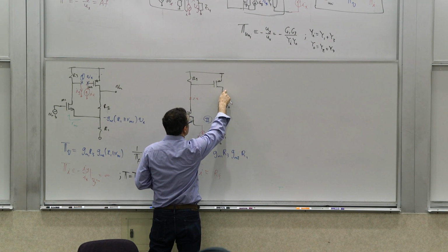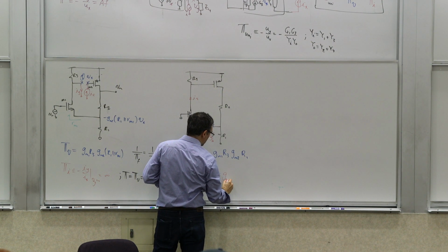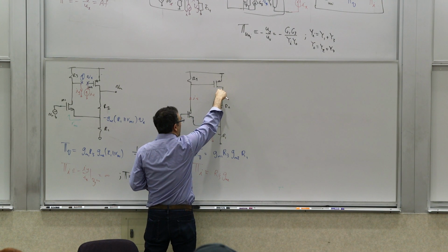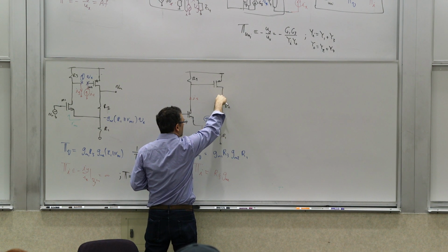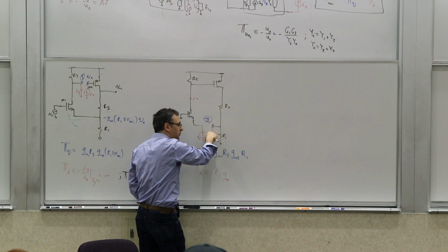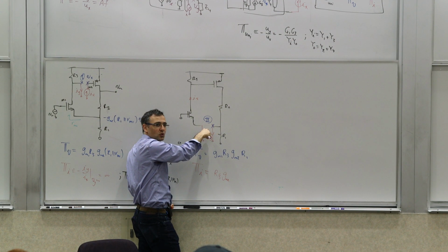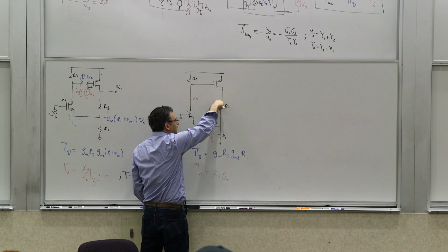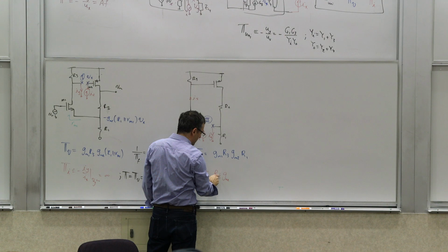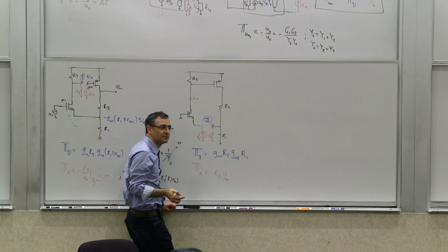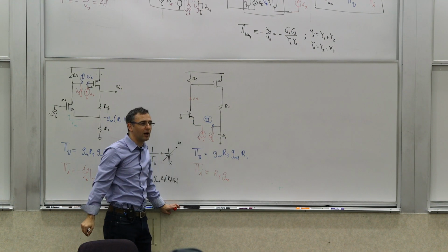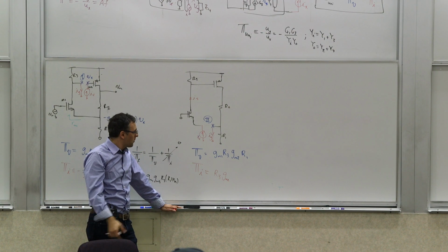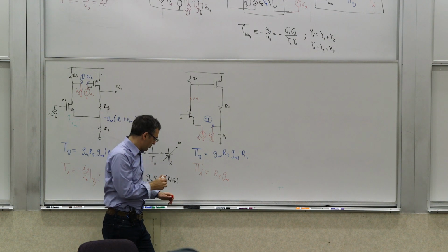And then that voltage would go through this guy, would give you a Gm2, and that would produce this current. Now, this current would be flowing through here, and all of it will flow through this short circuit, because the short will absorb all of the current. So that current, Gm2 R3, would go through the short, which would be the Iy. Is it clear? Does it make sense? So that's the current loop gain.